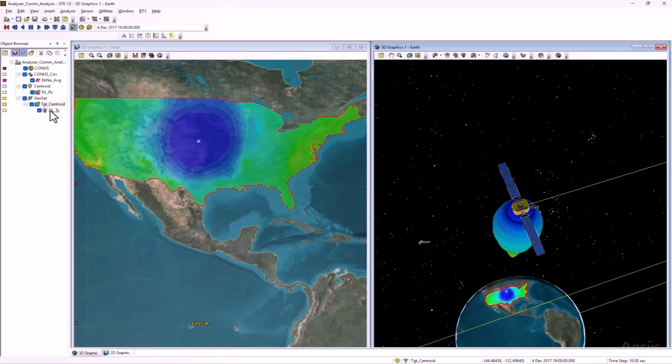And you'll see that that transmitter is nested, or is a child, of a sensor, and that sensor is pointed to a ground point of interest that we have called Centroid. Centroid is also where we are co-locating a complementary receiver object in STK. So this creates my point-to-point communication link, and I am then able to perform link budget parameters and analyses between that transmitter and receiver object. So if I were interested in carrier to noise ratio or received signal power, things of that nature, that computation makes that available for me.